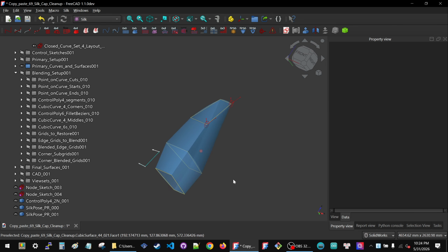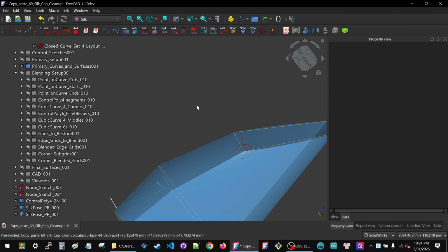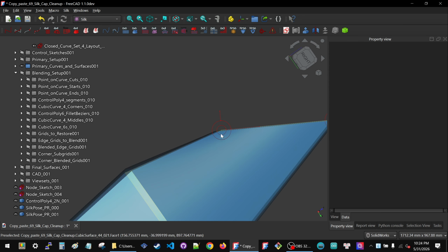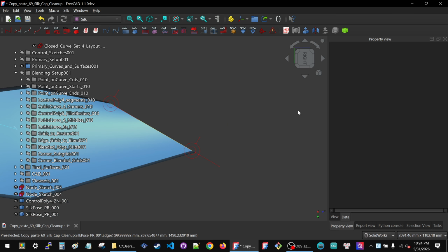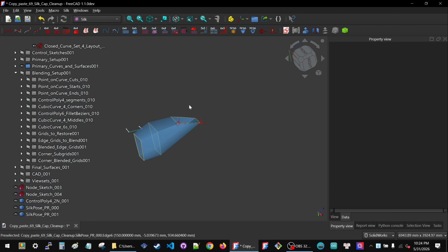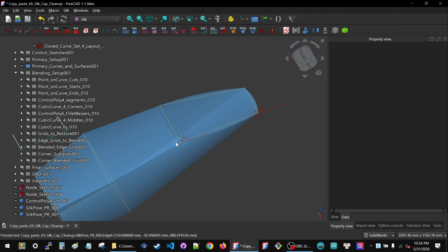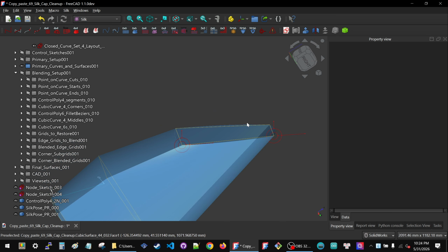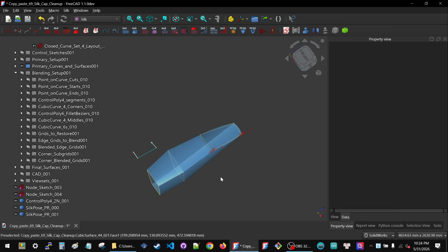So when I'm going to map these two sketches to these two objects, and when I edit the sketches, it will automatically put me in this alignment for one of the nodes and this alignment for one of the nodes. And the cool thing is it will look the same. I will have two sketches that are in different planes that control a 3D curve, but when I edit their sketches, it will put me in a standard orientation. And that's what I want for this object.